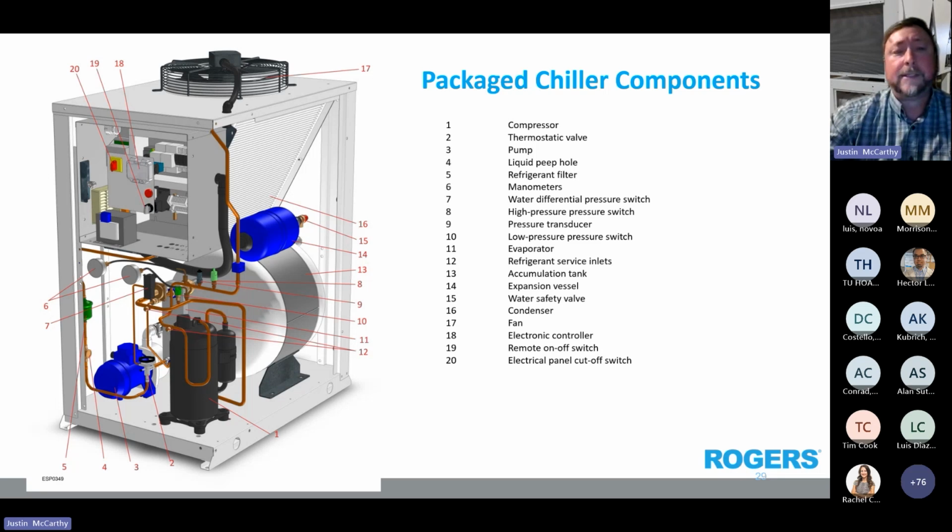The whole idea is to hook up your glycol or water connections and your electricity, fill the system and the external loop, set your temperature, and then we start up the chiller. A very simple all-in-one solution. A lot of chillers out there, you're going to find that they're custom, but they all have the same components.